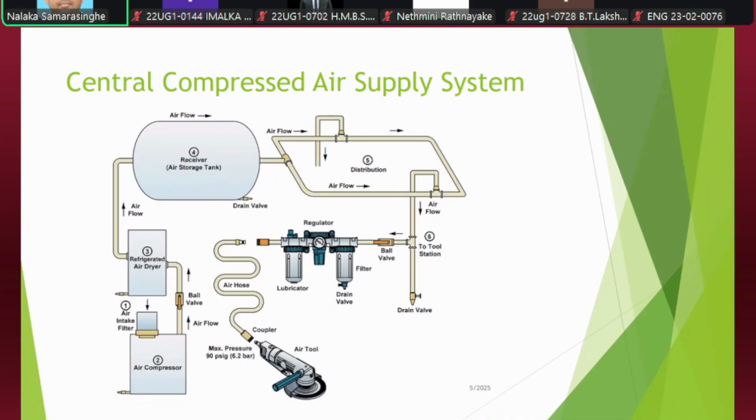That's one example, and also where we have some printing rollers to be engaged using pneumatic cylinders. To operate those pneumatic cylinders, you require compressed air. Usually in a production flow, the compressed air is supplied to various parts of the building with a network of pipes, usually GI pipes. A similar system is shown in this image.